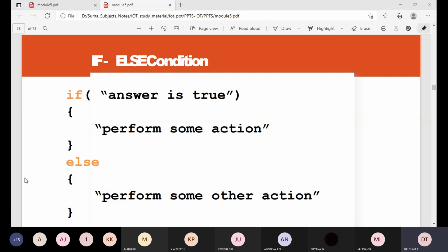Okay. So the difference between analog, digital and pulse width modulation pins. The analog pins have unlimited possible states between 0 and 1023. This allows you to read sensor values. For example, with a light sensor, if it is very dark, you will read 1023. If it is very bright, then you will read 0. If the brightness is between dark and very bright, you will read a value between 0 and 1023.